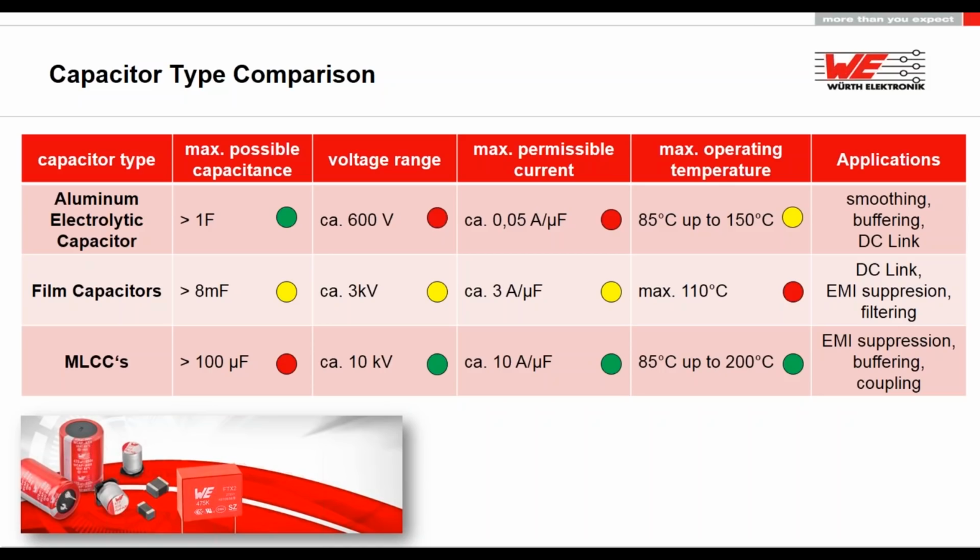You can go to the far out range. Sure, if you need more, you have to go for supercaps, but anyway, you will not find the voltage range for supercaps. For the aluminum electrolytics, also called E-caps, nowadays it's 600 volts, 650. It's very special, so I wrote 600 for the general, what you can find within the market.